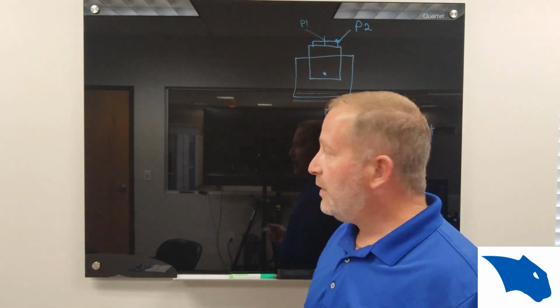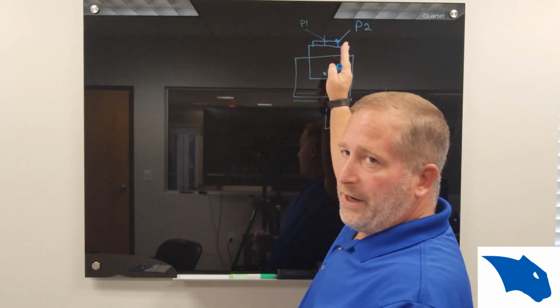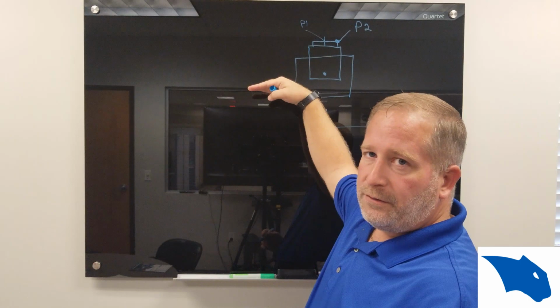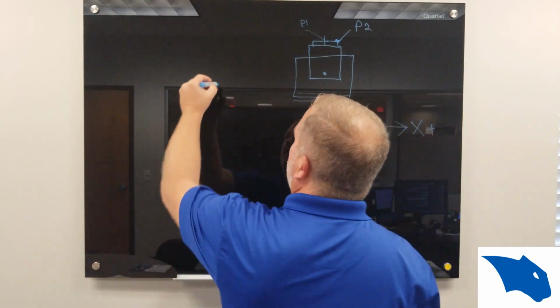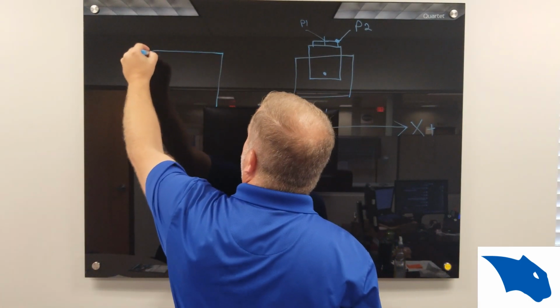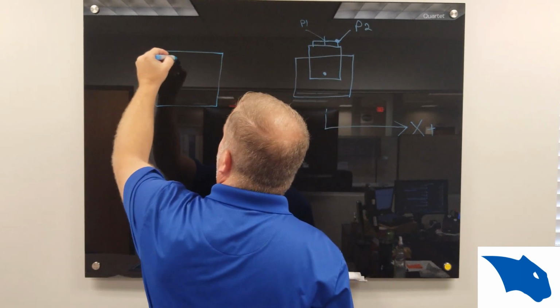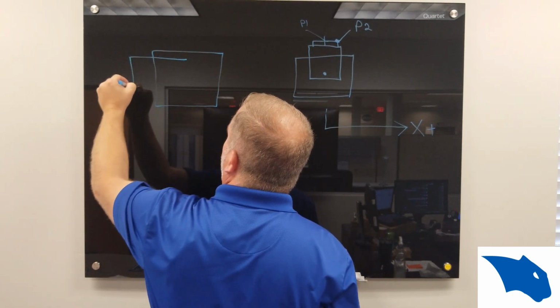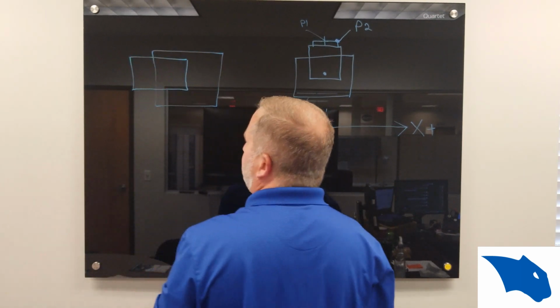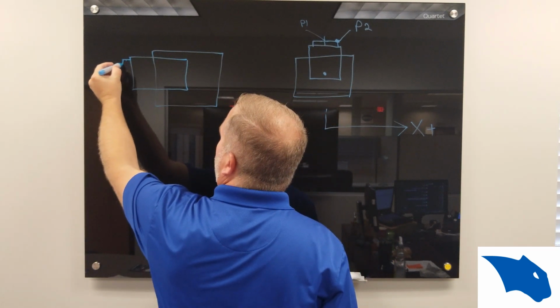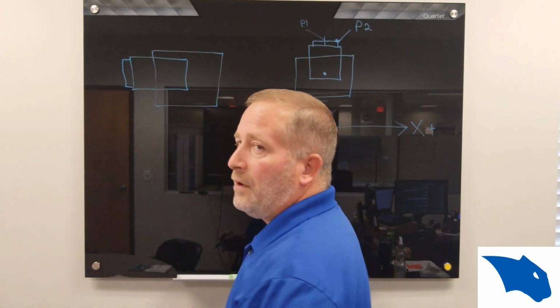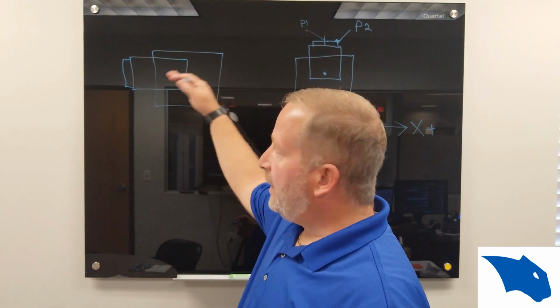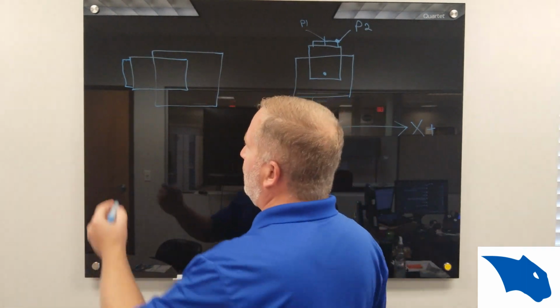The next step is to rotate the tilt rotary unit down 90 degrees. So we have our base, and we now have the tilt rotary unit tilted down. And here is our rotary platter. We want to find those exact same 2 points, but in the new position.